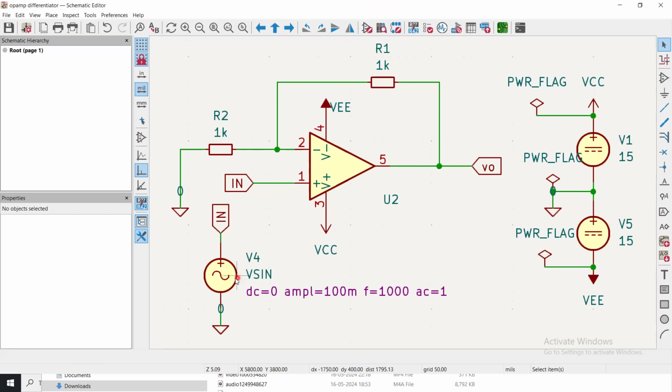I will have the amplified output at the output. And finally, if I configure this voltage source as an AC voltage source, then I can understand the behavior of the circuit in terms of its Bode plot, which is basically presenting me the frequency response of the circuit. So we will see through simulation all these analyses in today's topic.